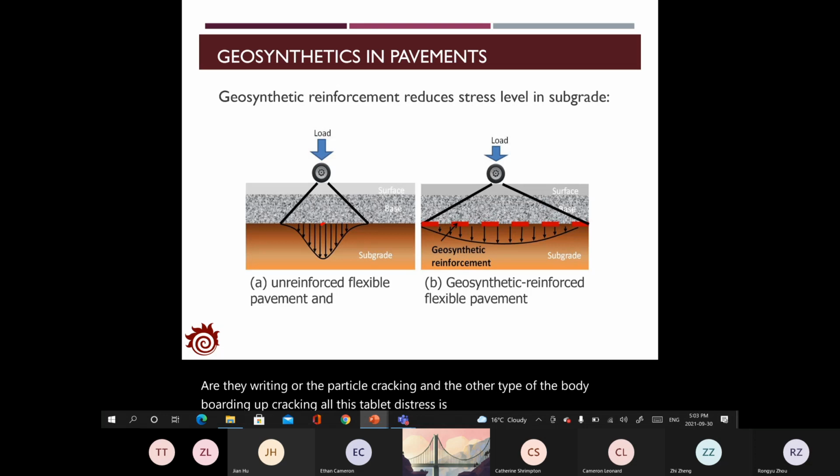to the pavement structure. But if you apply some geosynthetic reinforcement, like some geogrids or some geotextiles between the subgrade layer and the base layer, then the load transferred from the base layer to the subgrade layer will also be supported by this geogrid, and in that sense, the distribution of the load at the boundaries of the base and subgrade layer will not be that concentrated.